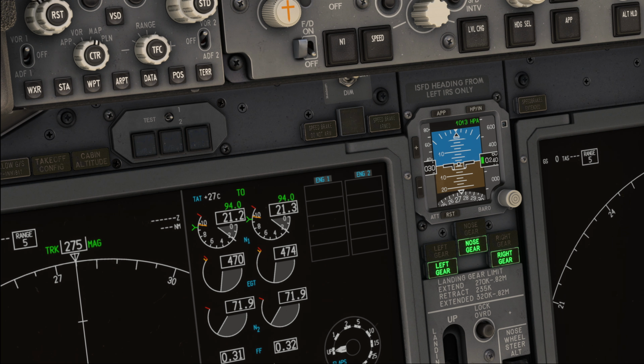Now there is also a new light that is the fuel flow light located at the very bottom of the stack. Now this one likewise did not exist on the 737NG, and these lights are to alert the crew of a possible fuel leak condition. The fuel flow alert illuminates when the difference between the actual engine fuel flow rate and the FMC expected fuel flow rate exceeds a predetermined threshold value for 5 continuous minutes. An example of this would be an engine consuming 1200 kilos per hour when the FMC is only expecting the fuel flow to be 725 kilos per hour.